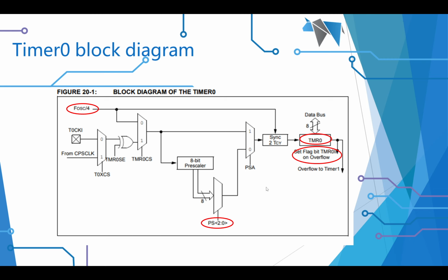Because here's the diagram from the data sheet with some circles on it. And essentially it says magic happens, but it doesn't really. Let's just bring up a pen. It's saying I can have clock sources, and the clock sources are over here, okay? They're in this area here, and they get fed into particular gates, and the clock then starts to increment.